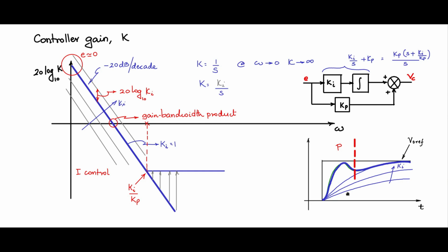How do I choose the values of Ki and Kp? The step is very simple. You don't include Kp first. You only start with Ki, and Ki a very low value, with Kp at 0. Keep on increasing Ki gradually, keeping Kp 0, till you get to a response with pure I control that is best. And then you stop at that value.